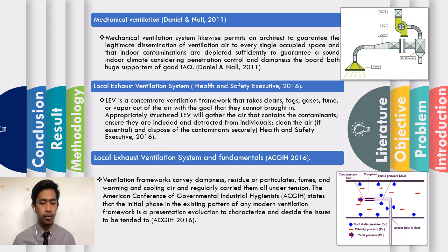The last one is local exhaust ventilation system fundamentals, which is to test the performance of the LV system. We have to collect the data, which is the total pressure, static pressure, and the velocity pressure.